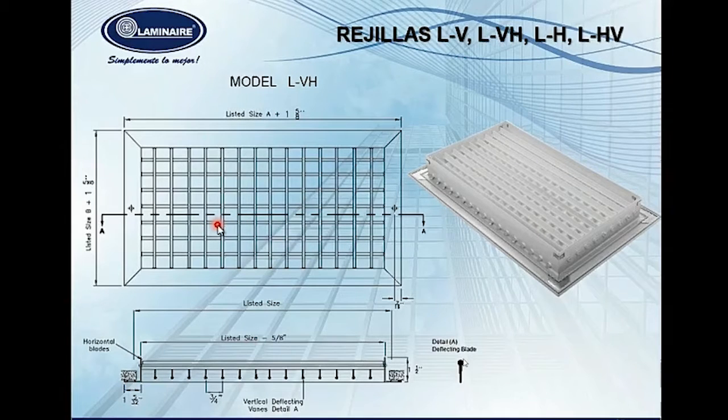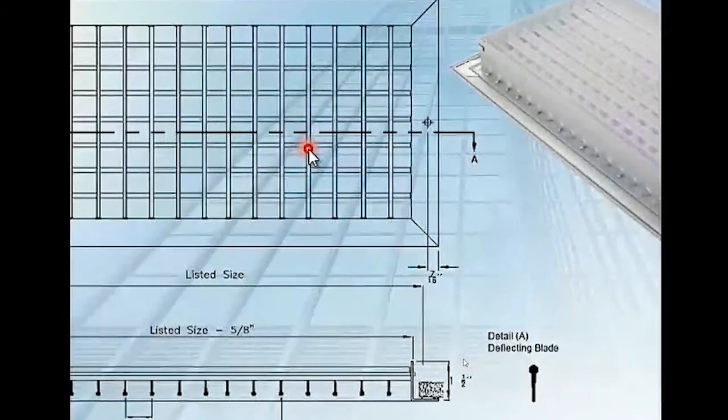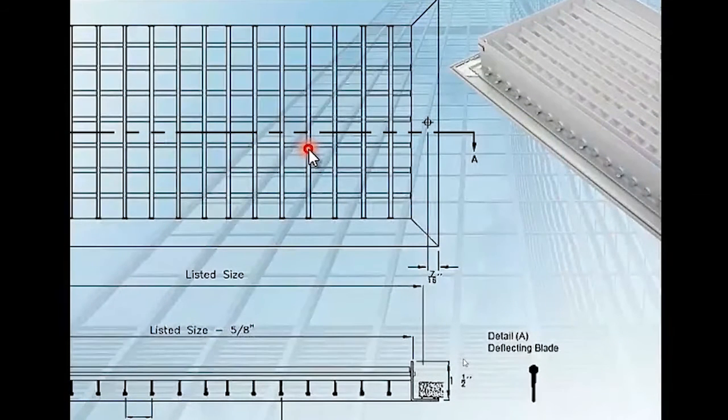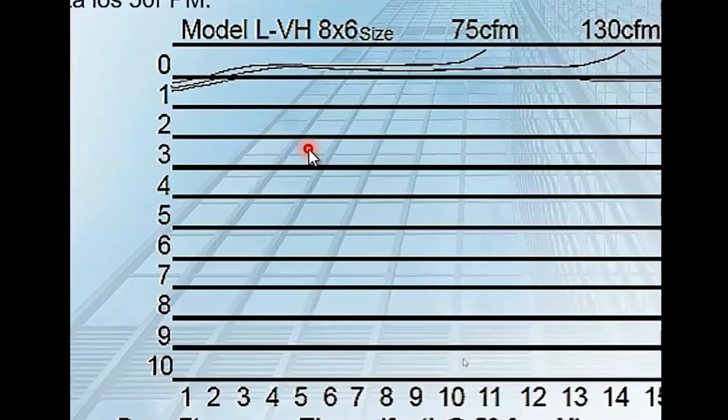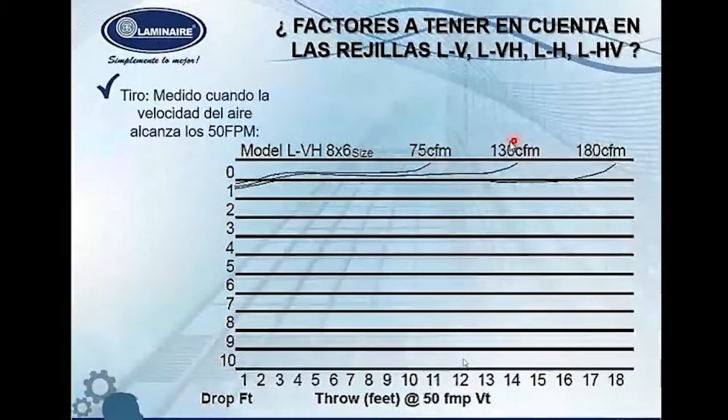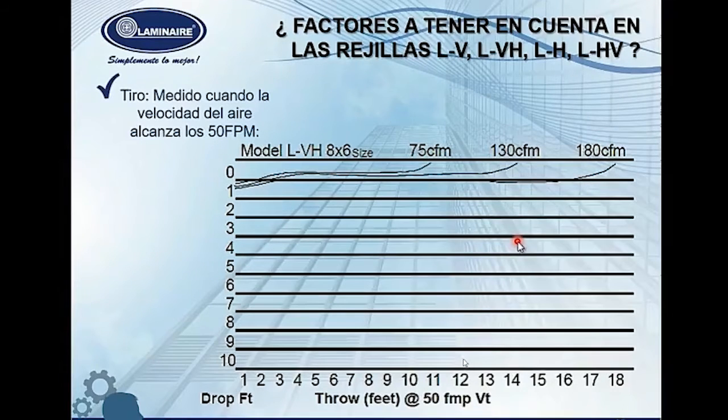When air conditioning is being used, the horizontal flaps have to be at the top because there is more density of the air. So we need the air to reach the bigger throws and then start falling down by gravity. Here we see a graph that shows us when the air is injected with low volumes, we obtain some throw in the grids that are over the diffusers. The grids are elements used to bring big flows or volumes of air to superior or bigger distances.